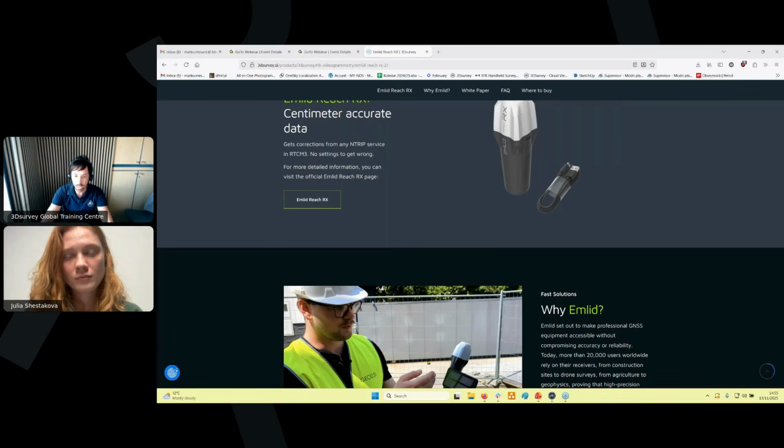If you would really like to have really detailed 3D models, because this model looks perfect from the perspectives you recorded, then of course you need to go a second time back, but keep in mind the idea of how drone mapping works. So move a bit away from the first line, and get a similar perspective to the first line, because in this way both frames from two positions can match in between.